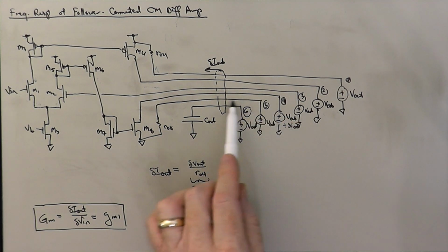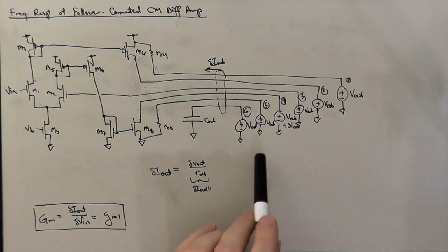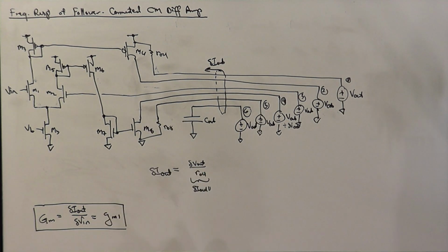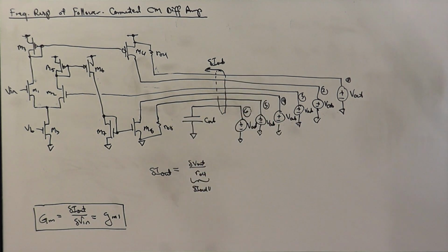Well, branch 4, what's that connected to? That's the drain of M8. Well, again, that's the drain of an ideal transistor. In this case, it's an NMOS transistor that's operating in saturation. We're encapsulating M8's early effect in RO8, and so there will be no current flow in branch 4 due to that change in voltage, and there's nothing else changing in the circuit. So again, we have 6 zero components due to delta V out on branch 4. So we've considered 18, which is half of the 36 possible components, and only one non-zero component so far.